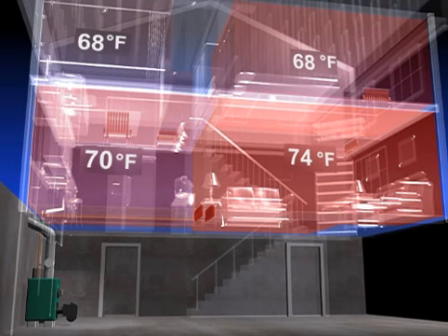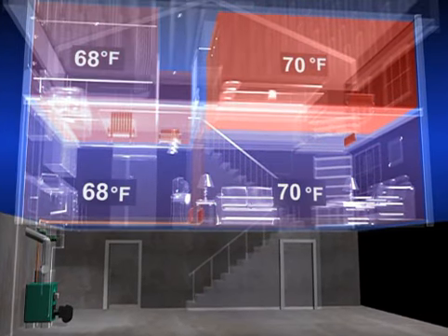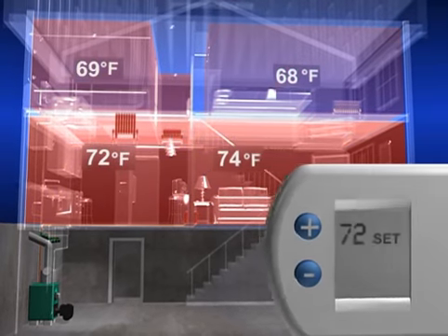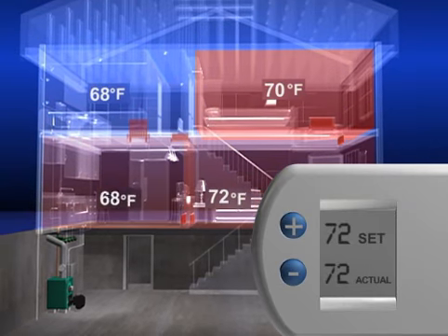There are more temperature swings in the heated space due to intermittent flow at high temperature. There are also more expansion and contraction noises when intermittent flow is used to control temperature. Using outdoor reset technology addresses each of these problems. Varying the boiler supply temperature instead of interrupting the flow of constantly high temperature water provides a reduction in fuel use and causes smaller temperature swings in the heated space and less noise in the piping.